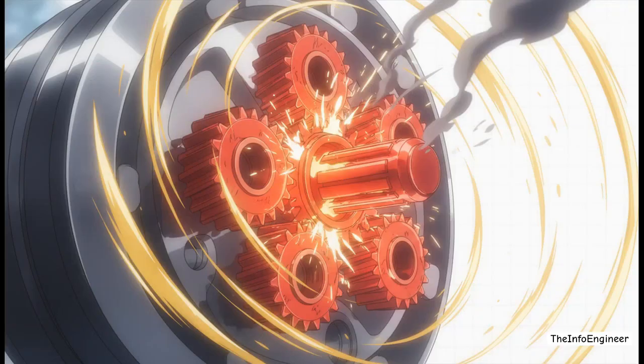And honestly, that leads to a catastrophic failure mode. Imagine you're stuck in deep snow, and you just floor the throttle out of frustration, hoping to break free. That extreme free spinning causes the spider gears to rotate on the crosspin at ludicrous speeds. It literally slings the differential oil completely away from the mesh points. You get severe metal-on-metal friction, massive heat buildup, and eventually the crosspin will heat score and literally weld itself to the spider gears. Boom! Drivetrain destroyed.